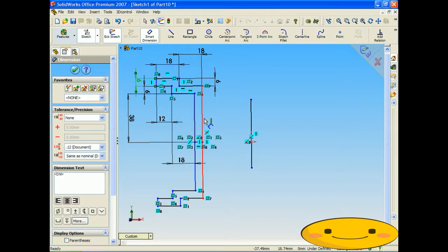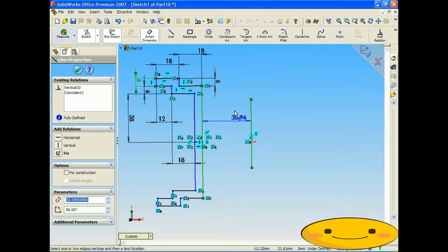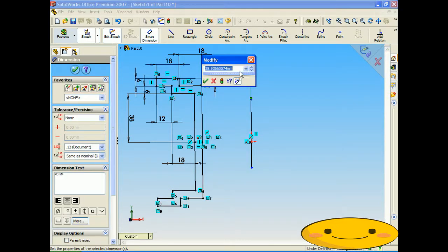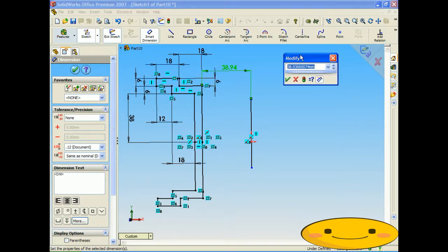For this one, from here to here, this is going to be pretty much the size of your rim. So you can think of it, if you want, a 300 millimeter diameter is going to give you like a 12-inch rim. So if you do 150 to the middle there, you're going to get a 300 millimeter diameter, and you're going to get like a 12-inch rim. So it's up to you. You can play around with it. I'm going to put 200 millimeters in here. Click OK.